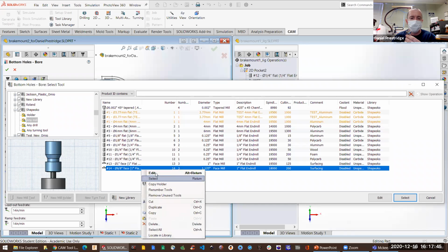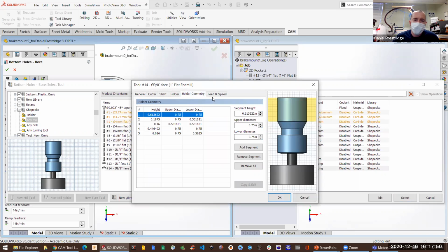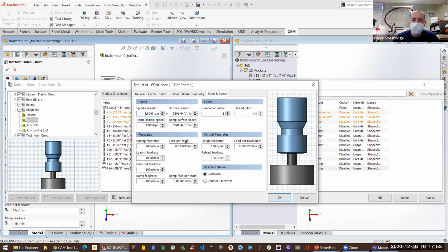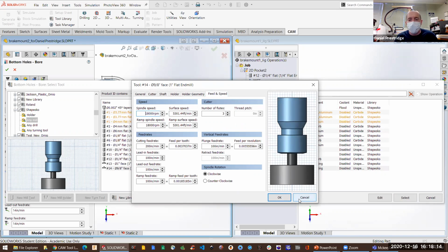And when you go into it, if you save these guys, they're going to save the feeds and speeds that they recommend from the manufacturer and from yourself, so that you move forward. And those offsets, you'll find maybe I can move 20% faster through my material than the manufacturer. Maybe I have to cut it in half. And if you update these, then you can continue using those tools into the future. So it's about setting up maybe the next people who end up using the same tools.